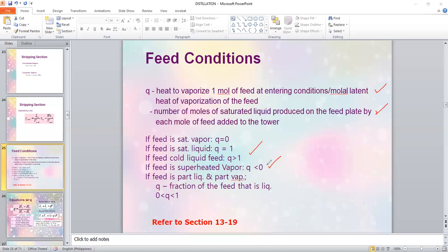Because whether we're solving the number of stages of your distilling column, that will tell us how high your column is in terms of design, and analytically or graphically, most of my students that have taken this subject, the main culprit always while the students have everything gone wrong is the Q. Meaning, all their computations will be wrong if this Q value is wrong.